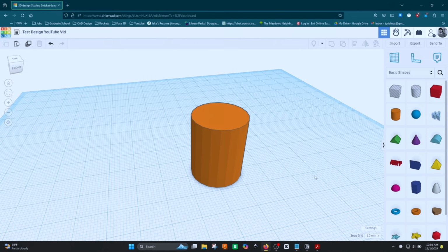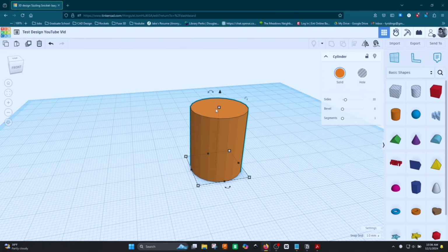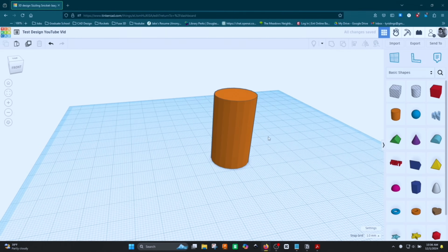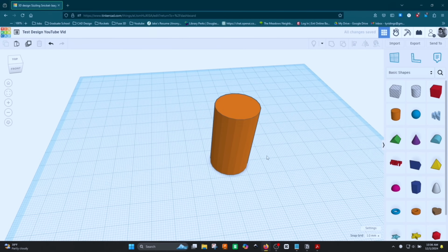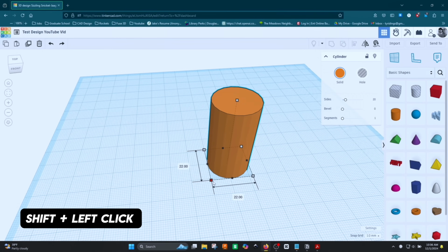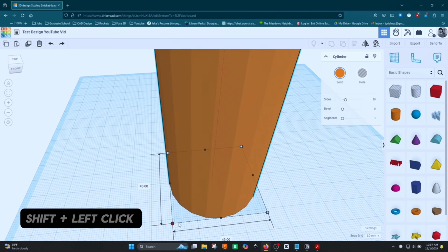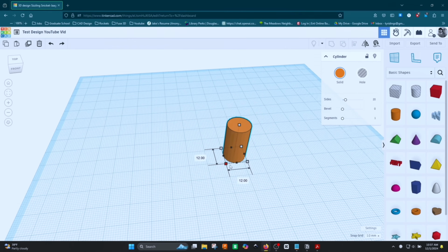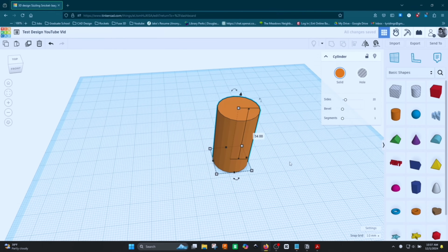Another way that you can do this, say proportionally you like the size of something. So for me, say it's this big and I proportionally like the size of it, meaning I like the length and width and the height. I just wish the whole thing was bigger uniformly. To do that, click on the part and hold down Shift and left mouse click on one of these corner white boxes and pull out to scale up or push in to scale it down. Okay, that's a really important tool that you'll probably use a lot. So highly recommend remembering that.